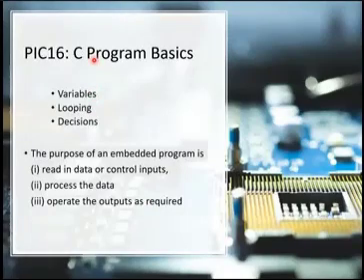So how do we transform back to packed and unpacked BCD? You can see here, to convert ASCII back to packed BCD, you must convert it to unpacked BCD first, to remove the digit 3 here, and then combine to make packed BCD. First convert to unpacked by removing the number 3 here.